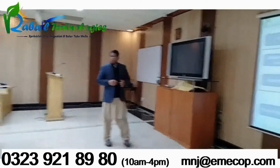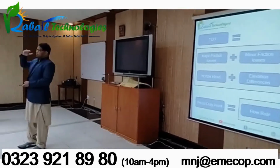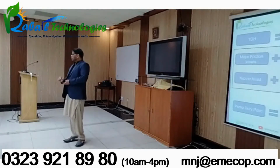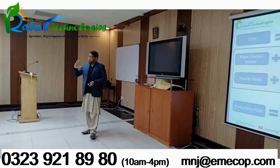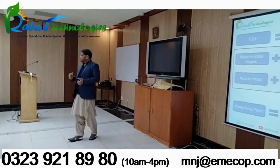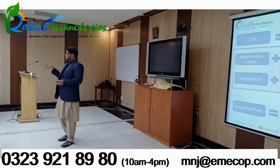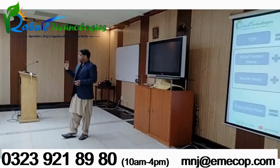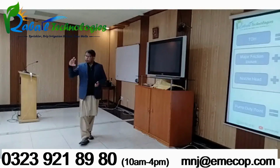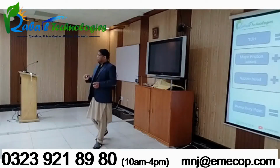What is suction head? Suction head is basically the vertical difference between the impeller eye and the water table or the water level. That vertical height can be 6 meters at the most that we recommend. Most of the time in Pakistan, unfortunately, you can see even 7 meters, even 10 meters. But in that case, the pump will cavitate. Practically, we take it as 5 to 6 meters, not more than that. So that will be the elevation difference between the impeller eye and the water level.